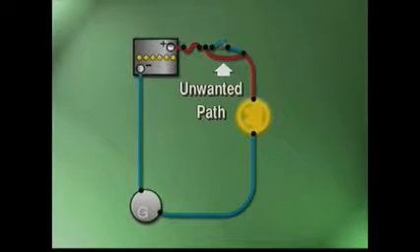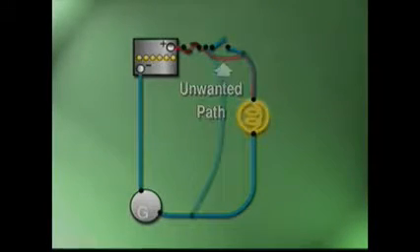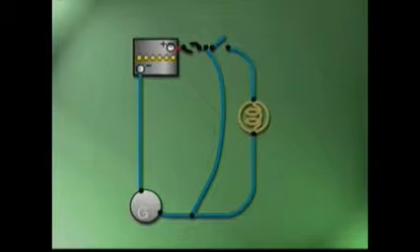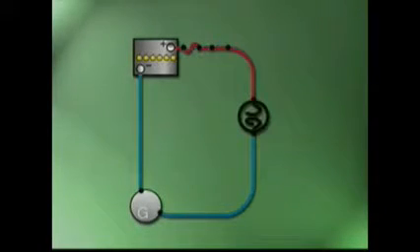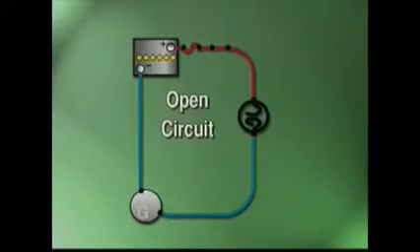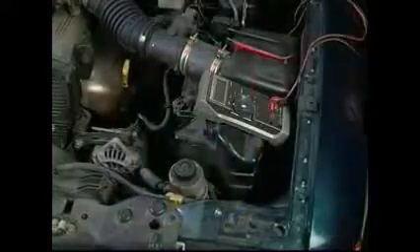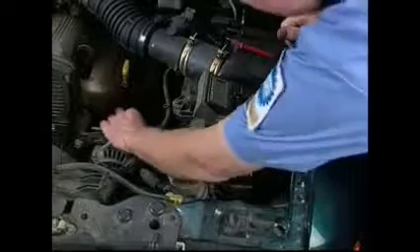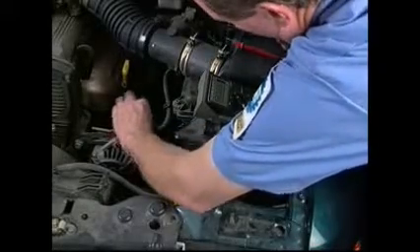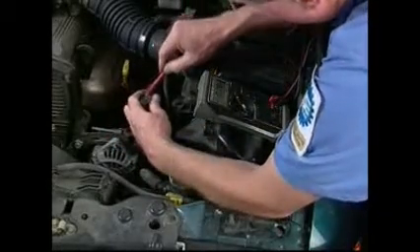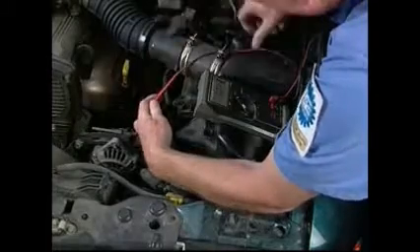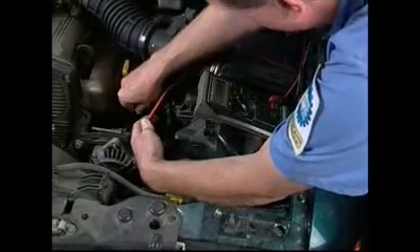Short circuits are probably the most difficult electrical problem to troubleshoot, especially if they're intermittent. If the circuit is shorted, you won't be able to use the voltage drop method because current must be flowing for voltage to drop. In a short circuit, there's usually no current flow because the fuse is blown, creating an open circuit. In addition to open and shorted circuits, there are other common circuit faults such as a loss of power, improperly working components, or inoperative or improperly operating loads.